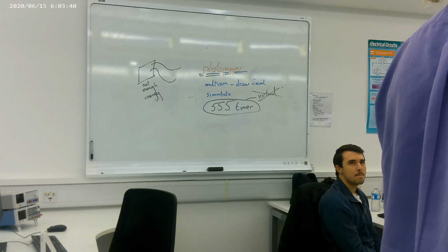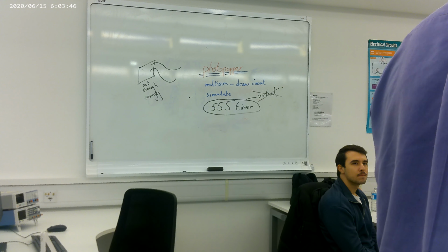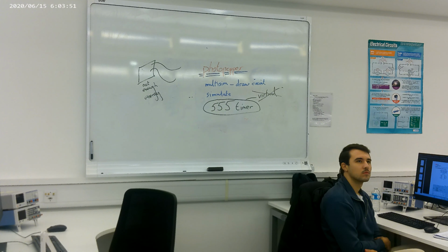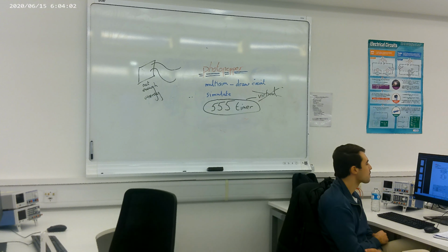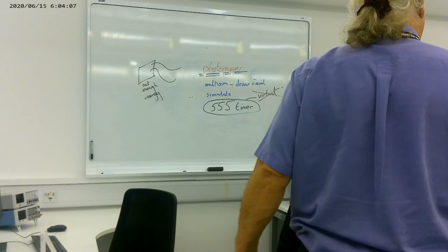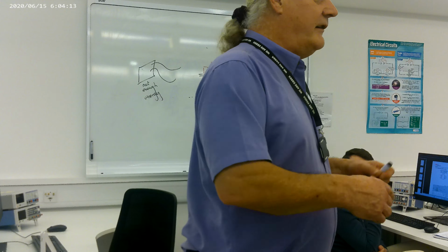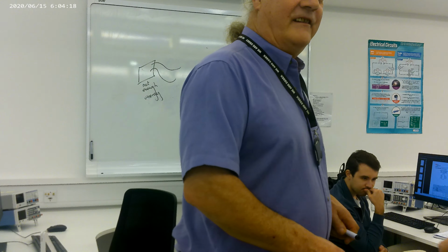This will have an open circuit voltage, and we'll plug it into one in a minute and measure it on the multimeter. In other words, if you're not driving anything apart from measuring it, in this light, do you want to wire that up? Might be easy to get a multimeter from the opposite. And we'll shine your mobile phone into it in a minute, and you'll see, yahoo, it's got 3.5, 4 volts coming out. It's brilliant, the problem's solved. Well, it hasn't until you try and drive something with it. You put the motor on it, it collapses. So it doesn't generate 4 volts when it's under load, it generates nothing when it's under load.